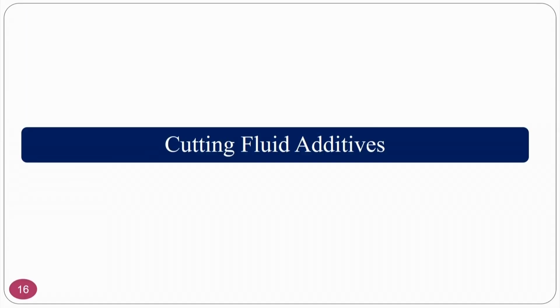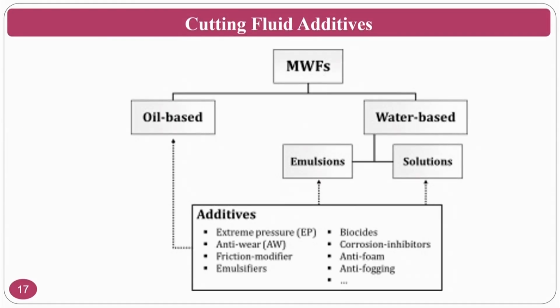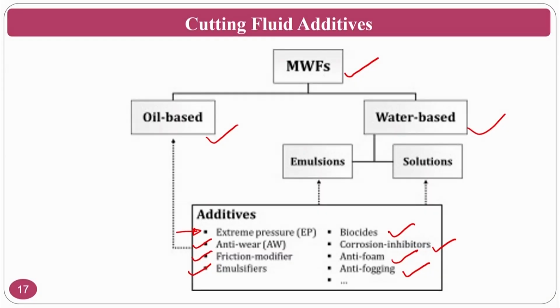Cutting fluid additives: the common name is metal working fluids. There are oil based and water based. Oil based fluids or emulsions are solutions where you will have extreme pressure additives, anti-wear additives, friction modifiers, emulsifiers, biocides, corrosion inhibitors, anti-foaming agents, anti-fogging agents, and many more, among which some are important, which we will see in the upcoming slides.